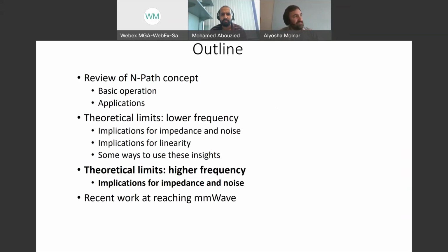Now, what I will say that we've seen is that all the loss mechanisms I've described with our shunt and stuff, that is entirely still true for the current mode. So even if I set the output to look like an AC ground, that shunting loss is still there, and it still effectively generates noise and degrades your performance. So that model is completely general, regardless of what you do on the baseband.